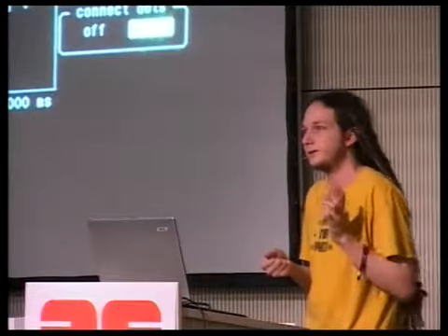So usually the chip will look at 0xFFFE, take those 16 bits and push them into the program counter. By doing it this way, it instead looks at 0x0C02. And then on different chips, you do different lines. Looking at a scope, you can see the timing. And once you initialize it, it's waiting for 0x80 to be sent across, because it needs to figure out the timing with which it's going to speak.